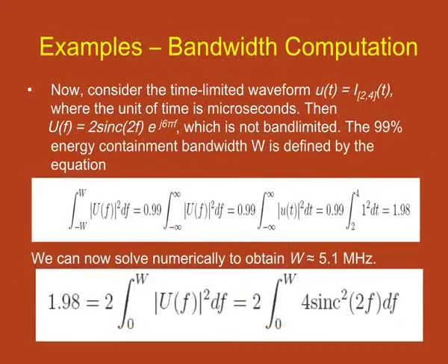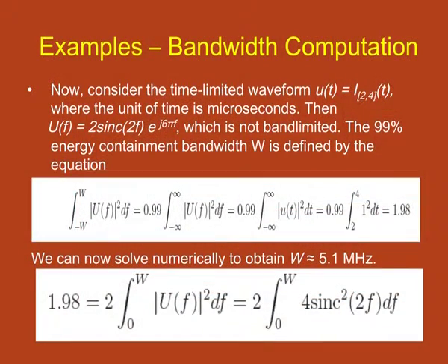Let us take another example. Now, consider a time domain waveform which is limited in time. This is a more practical case, because the previous waveform was a sinc, which extended from -infinity to +infinity in time, not realizable, and that is why the frequency response was limited, but that was more of theoretical importance. Now, what we are seeing is one of the most commonly encountered communication signals, which is called a gate pulse.